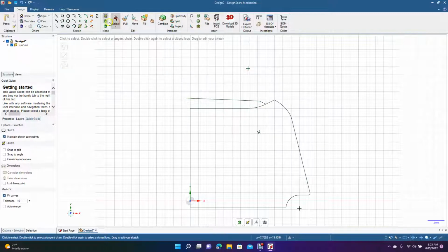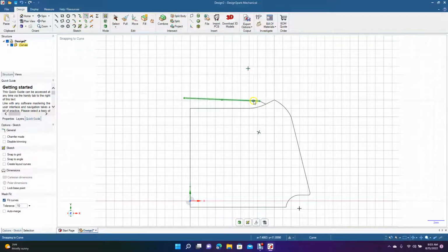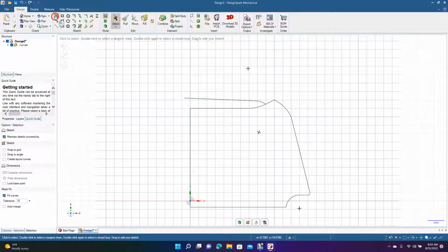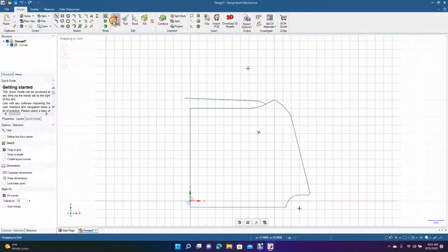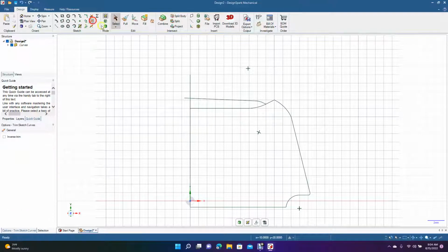Like this. Okay, now you're going to go create rounded corner. Let's put a rounded corner in there. Let's go ahead and get our line here. Let's turn on the snaps. Check that box. Select the click off, get the trim away. Actually, that line's not straight. I'm going to get rid of that line. Then we're going to put a new one in there. Go from the endpoint. Just overdraw, or draw through, and then we're going to trim.